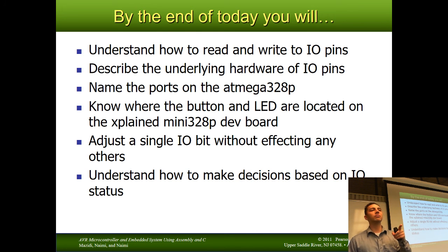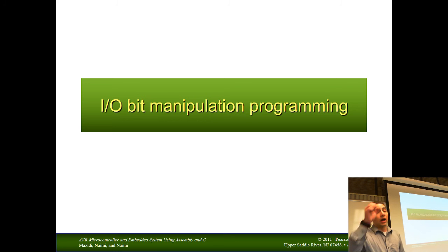No, we don't toggle high impedance and pull-up. That's writing to the port register. We do toggle the actual output. If you're set up as an output and you write to the pin register, that toggles from a 0 to a 1. Okay. But that affects all of them at once. We have to write 8 bits at a time. So let's skedaddle on to I/O bit manipulation.